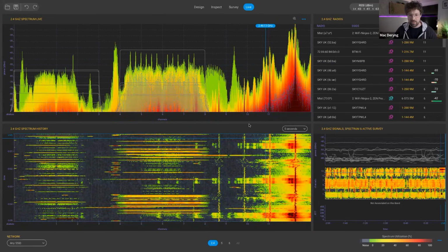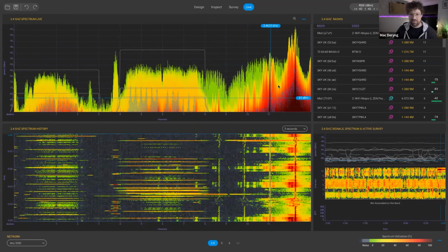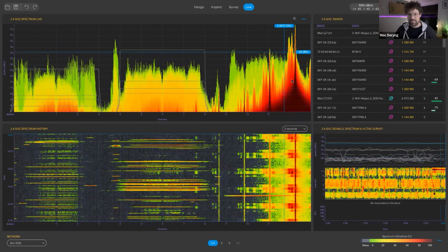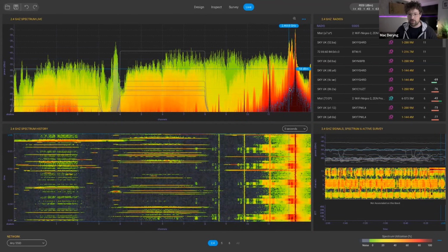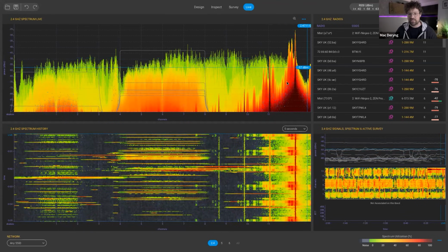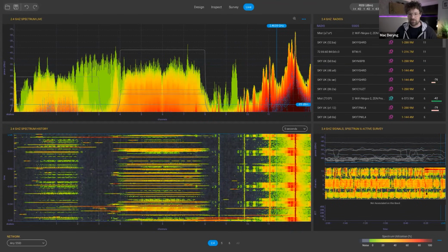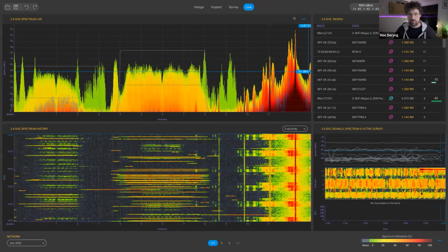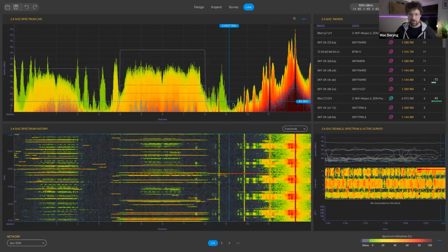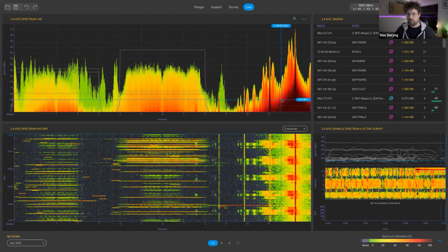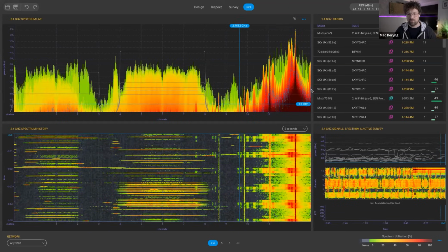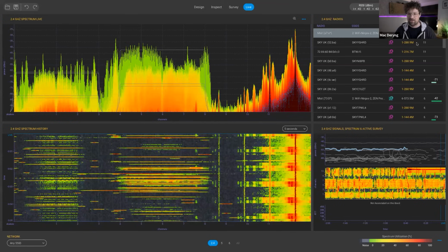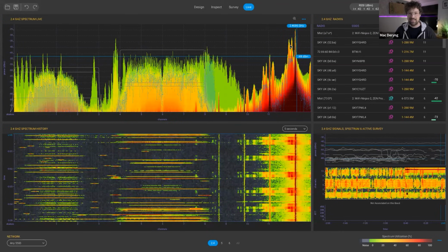So what's happening there? You can see around channel 11, we have quite a lot of red. And this is a typical look of the camera. The main spike is a video stream, and the small spikes on the left and the right-hand sides are the stereo audio from that particular camera. Now, another thing that is worth noticing, what happened to my beacons on channel 11? I used to have my Mist AP on channel 11. I could hear my neighbors on channel 11. I can't hear them anymore.